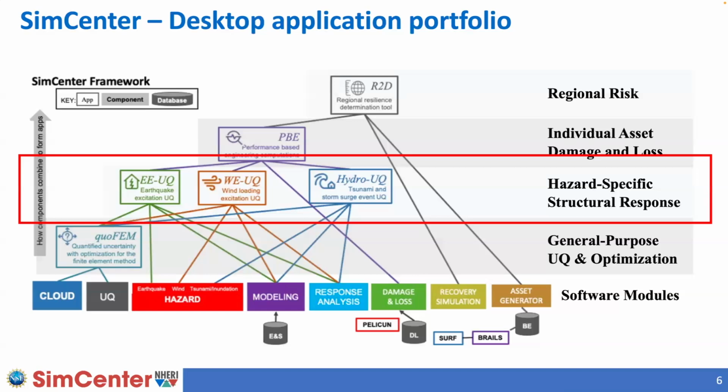And for wind application, we have a computational fluid dynamics, CFD, replication of the wind tunnel. It helps you to estimate the wind pressure anywhere surrounding your building. And you can use that as an input to your structural analysis model.